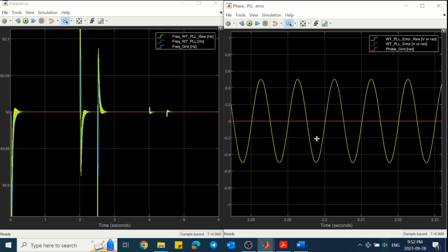And the measured voltage, which is the grid voltage, has a frequency of 50 Hertz, which means it is shifting the ABC signals by 50 Hertz when going from the ABC to DQ domain. So the grid signals, which have a frequency of 50 Hertz, will be observed as DC values in the DQ domain. The negative sequence already has a frequency of minus 50 Hertz. If we shift it back by 50 Hertz, it will be 100 Hertz, because it is already negative and we are making it more negative. So it will be 100 Hertz.